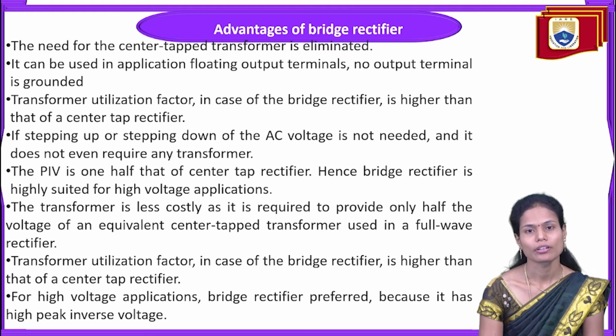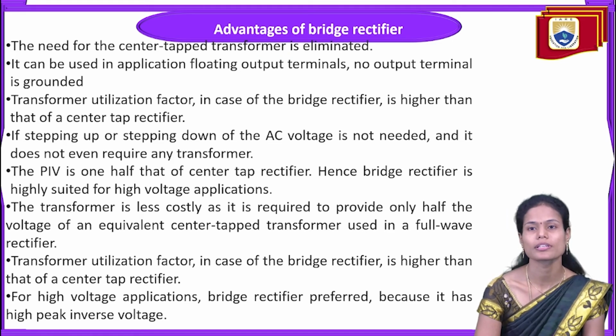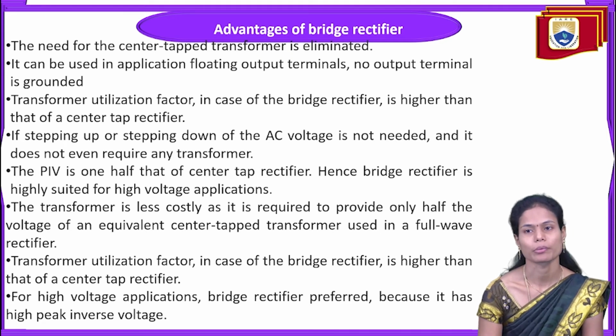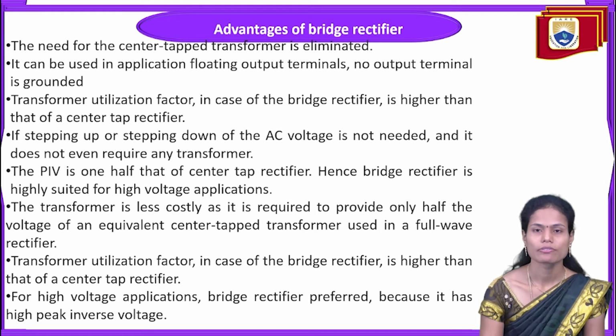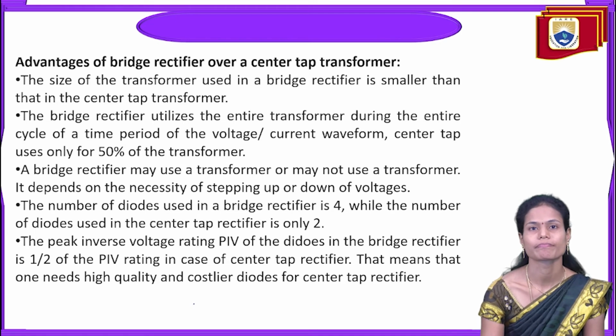Since we are not using any center tapped transformer, only the bridge is suitable for this. The transformer is less costly, as it is required to provide only half of the voltage of an equivalent center tapped transformer. The transformer utilization factor is high, and we can utilize this for high voltage applications.